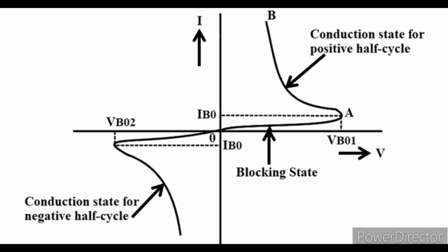And not only this, because there is no control signal in the DIAC, we can't make the device off whenever we want to, like a switch. The device goes into non-conduction only when the current drops to a level less than the holding current. So, because of the lack of control, the DIAC cannot be used as a switch.